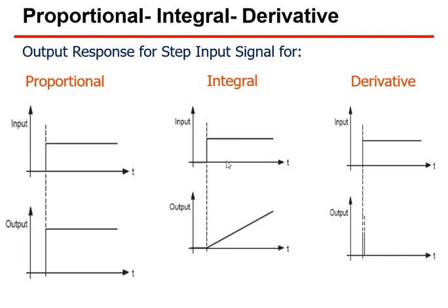Please understand this. These are the basic signals, which are very important to understand the next points as well. As I discussed earlier, for the step input the integral gives you an increasing slope. If it is a derivative, for a constant signal, you get a derivative like this, and I think you have studied the derivative of a constant. So the basic idea behind proportional, integral and derivative is given in this picture, and it will be very useful to understand the next concepts.